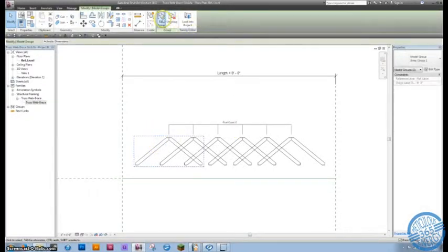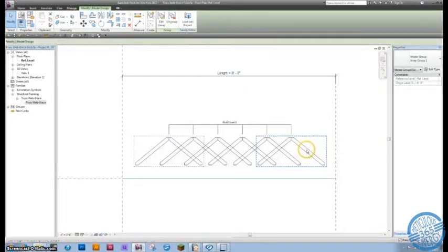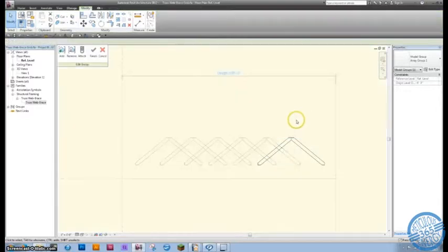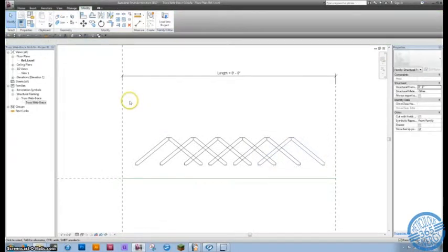Some people will be tempted to edit the group's first element and try to do the align in here, and then go to the last element and do the align in there. The issue with that, however, is that you will often get over constraints in your sketch, and it will break in funny ways. You open yourself up for more problems than you're worth. So I would just do it outside, in the main portion of the family.